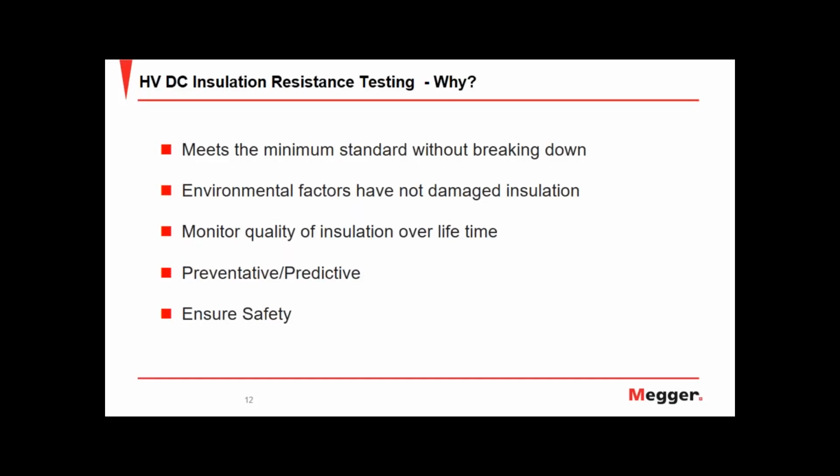So why do we actually do IR testing? Well, first of all, we need to make sure that it meets the standards without breaking down. That could be a standard set by a manufacturer, or it could be a utility company, for example, that has defined standards which they want you to pass. We want to make sure there have been no environmental factors that have damaged the insulation over time.